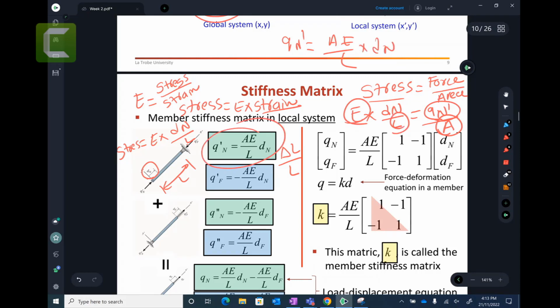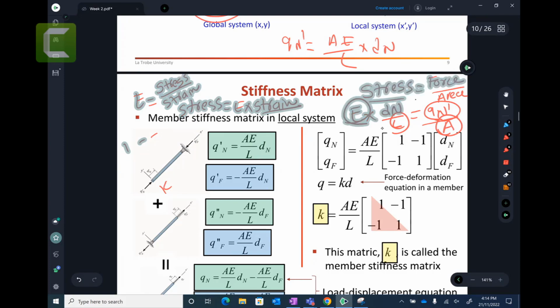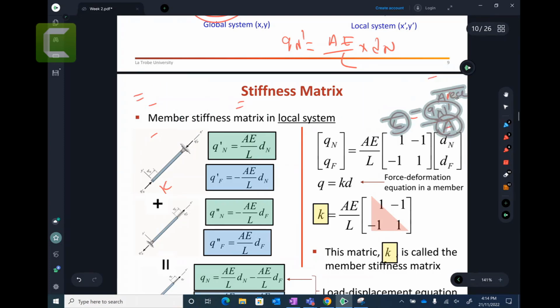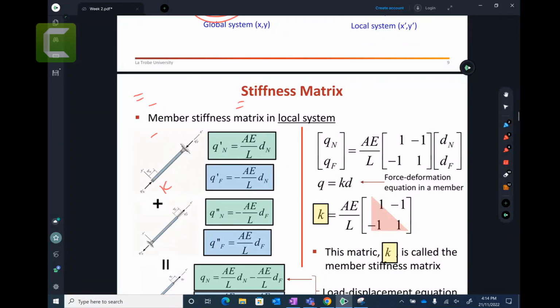Look at that. Right. So that is just the proof that this is the force times displacement. Area, how much cross-section area you have, whether it is rectangular, square, circular, you can find it. Young modulus, what material it is made of, if it is steel, concrete, or aluminium. It has a Young modulus value based on its stiffness, how stiff it is. If you apply force on that, is it deformed very easily, or is it not deformed very easily. That is the E definition. The higher the E, the more difficult it is to deform. That's what it's representing.